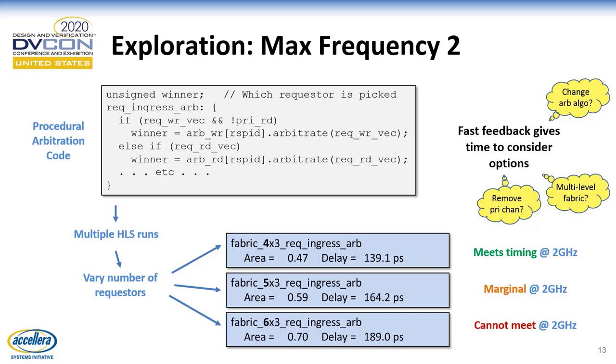So very quickly, we can give this type of sequential code. This is one benefit: this is just procedural code, write it how you like in C++. And at the end of this, you should have chosen who wins your arbitration. Now, in the RTL design, this might be spread across multiple arbitration modules. It's a bit more piecewise how you get the timing there.